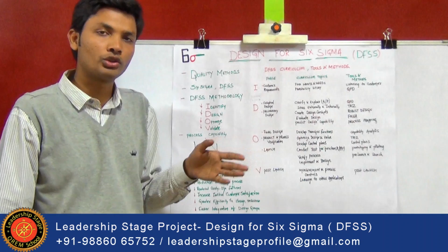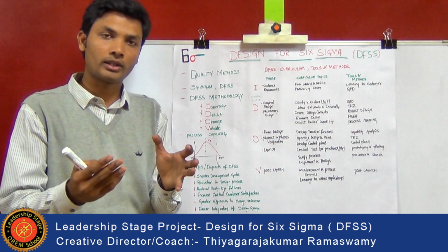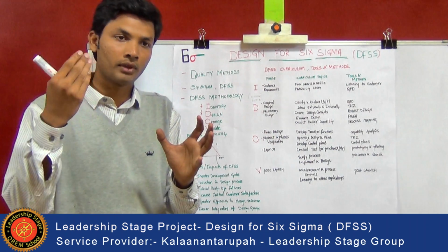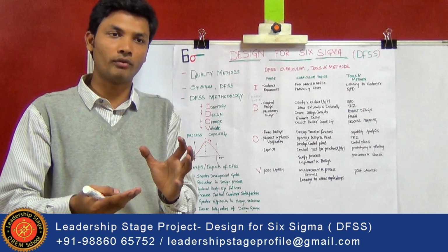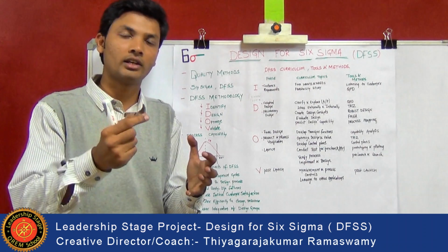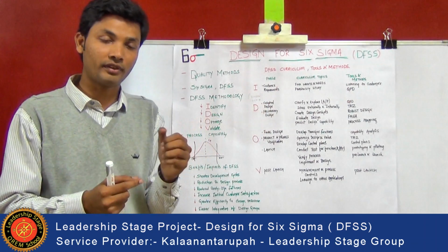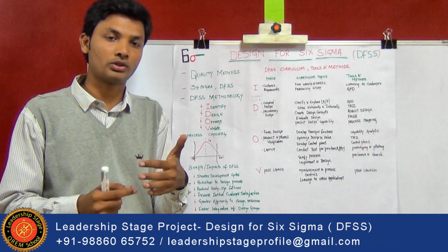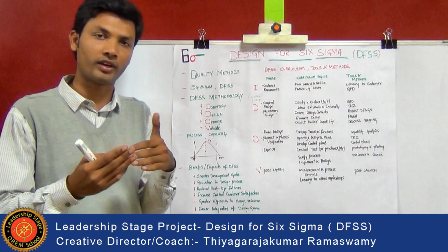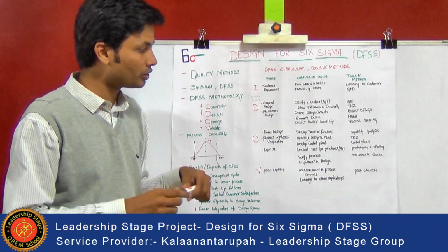And process mapping is one of the methods we use for selecting the manufacturing process. Like if there is a product where you have a choice between 2 or 3 manufacturing processes, either injection molding or sand casting, or else turning or boring, then there is an industrial method, which is nothing but finding the manufacturing process risk. Once you get that, it will be easy for you to decide which manufacturing process will have the least risk. That can be found out by using the process maps, where you will also finalize the surface finish of the component. So that is the process mapping.